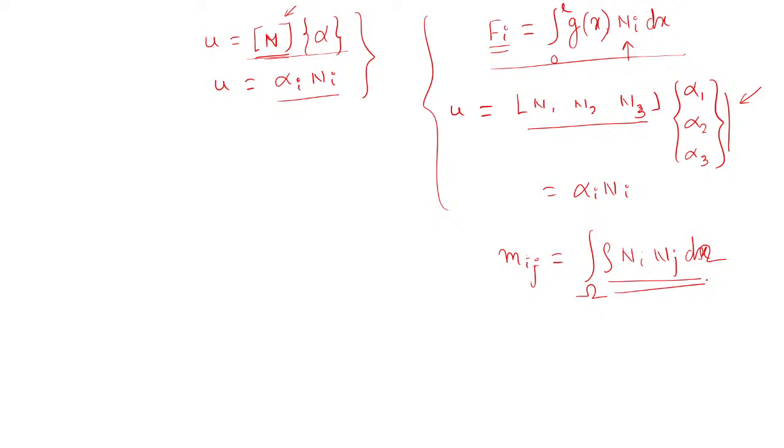So you simply integrate rho N i N j d omega. I am talking in terms of index notation, which was introduced in the previous lectures by Professor Arup Nandi. Either you can stick to index notation or you can use matrix notation, and you will be able to calculate the mass matrix. I think in one of the problems we asked for this. For the unsteady problem you need to calculate the mass matrix. You can find that problem and solve it again, and that will help you.